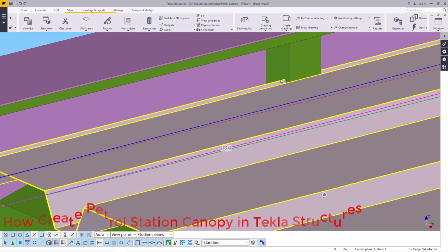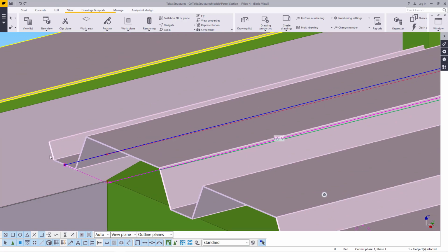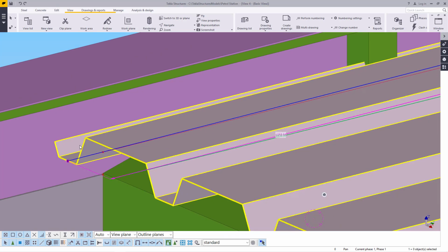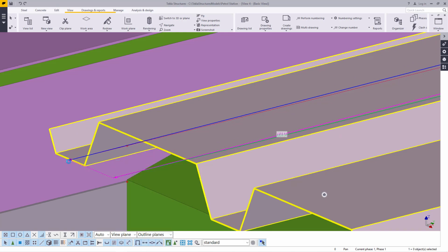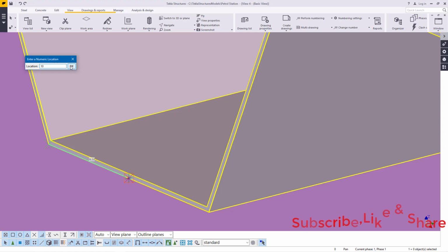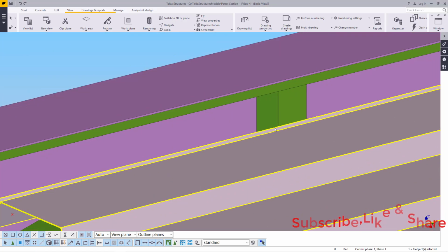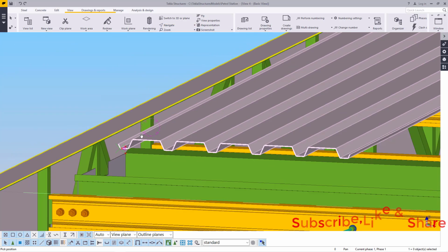So at the far end here, you can see also there's a clash with our girder that holds the barge flashing. So we'll shift it slightly by a millimeter amount. So what we're going to do, you just select on this, come to move. We'll give it a slight move from that spot to this spot by maybe 10 millimeter right there, and we'll be off that member. And that's okay.